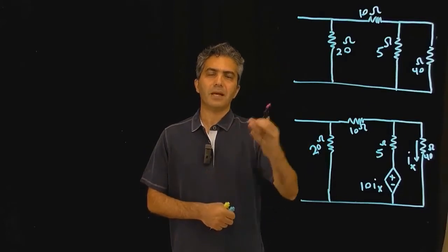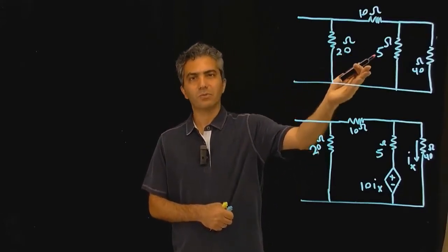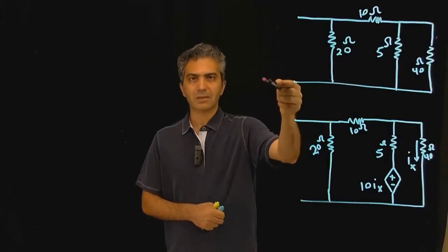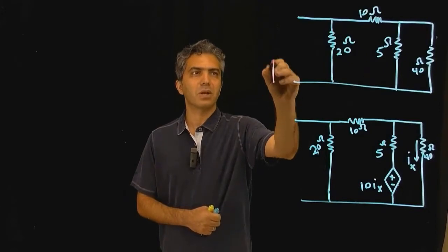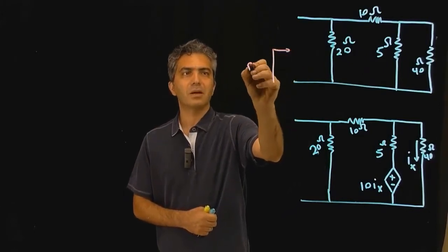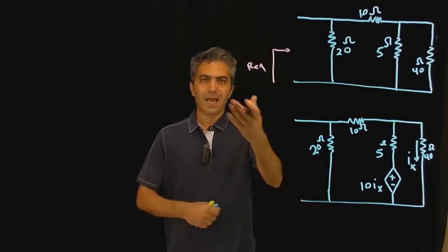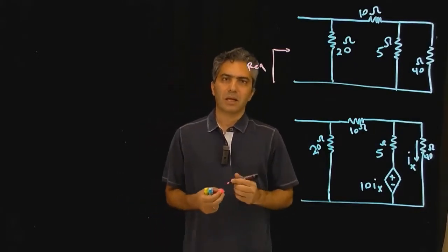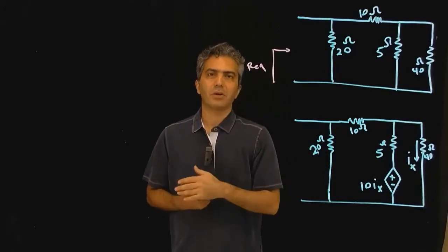And basically that question is the same thing as calculating the equivalent resistance for this, because the second step for the Norton or Thevenin equivalency was to now calculate the R equivalent, and that R equivalent would be your R Thevenin and your R Norton. They're the same thing. So how did we calculate R equivalents?